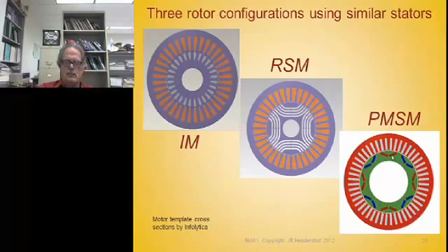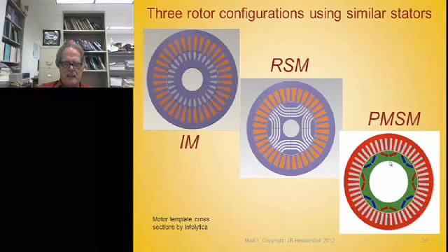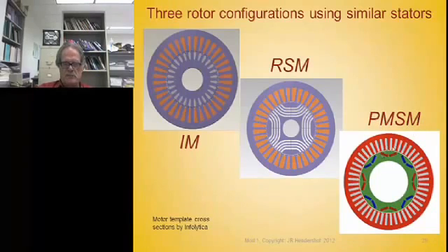So this particular one is called an IPM, internal permanent magnet machine. This is a permanent magnet synchronous machine with IPM rotor configuration. The magnets could have been on the surface up here, but they're inside, and they're shaped in a V, so we can spread them apart and get this soft iron in between, which gives this saliency. So those are the machines that we're going to study.